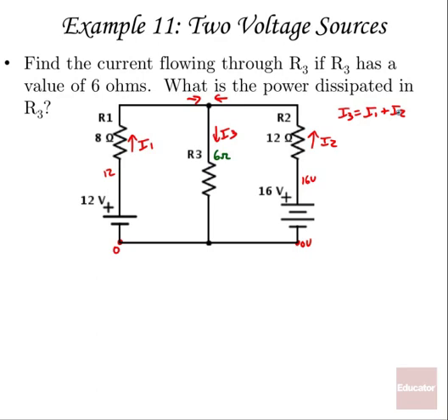All right, now that we've established that, let's see if we can't apply Kirchhoff's voltage law around some of these loops to get us some more information. If I apply Kirchhoff's voltage law around just this loop here, what that says is the sum of the potential drops around that loop must be equal to 0. So I'm going to list the positive and negative sides of each of these. This will be the positive side of the battery, the current of the resistor, the current is flowing and dropping potential this way, plus, minus, plus, minus, plus, minus.